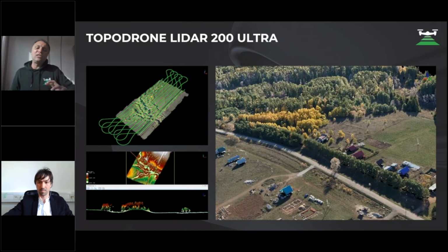And as you can see, it is better to see the point cloud in RGB colors. And this is why we have to find a solution for how to combine LiDAR point cloud together with photogrammetry data and how to colorize this point cloud. And this is why we chose 3Dsurvey, not only because of the opportunity to colorize the point cloud, but because of the wide tools to vectorize data, to create CAD layers, to create contour lines.